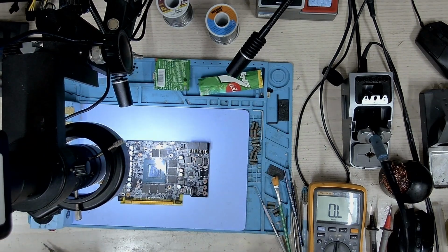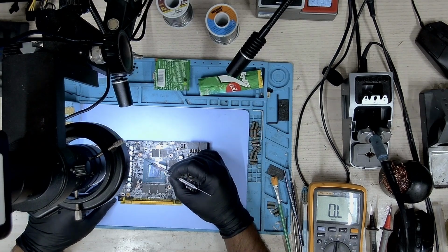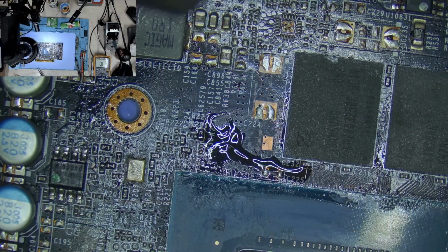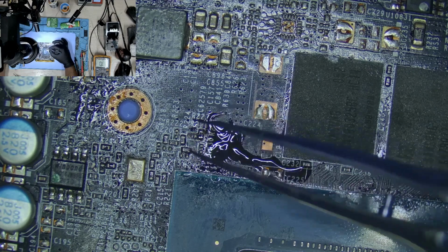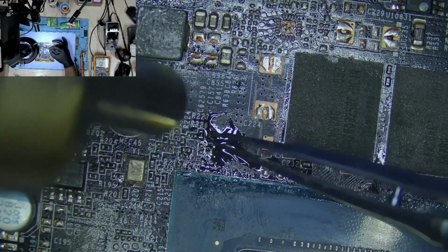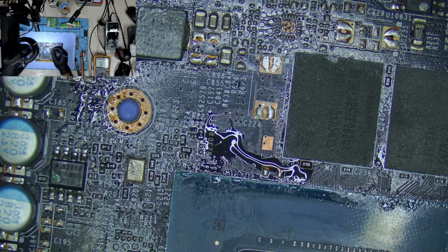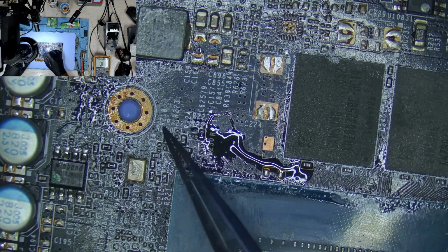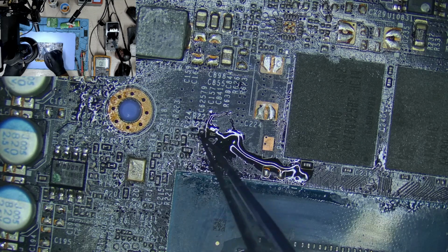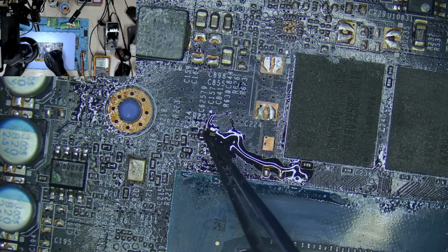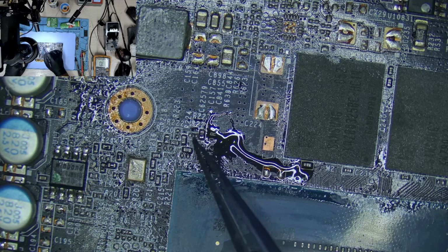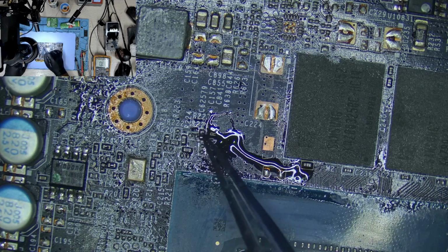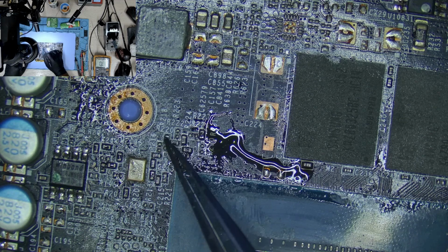So if you're not aware, these are the straps. It looks like the camera was not in the right position, so I'll explain it again. Okay, so these are the straps. Now what we are going to do is move this resistor. This resistor is in the high position and this resistor is in the high position. There are three resistors which are normally at high position. So this one is 101, which is for Hynix.